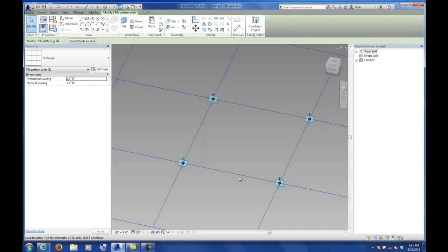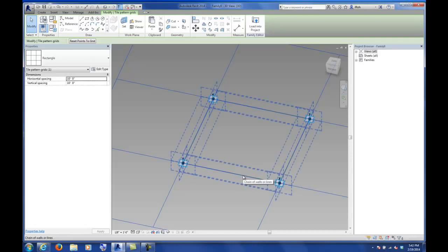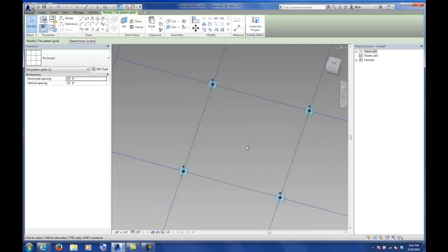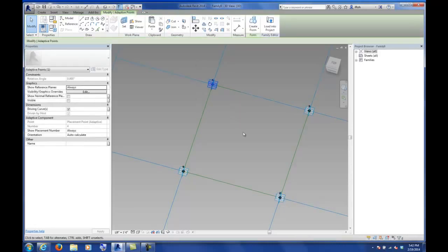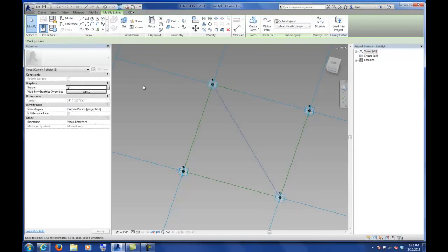And so I'm just going to do a quick little die-grid, which is basically a rectangle or some kind of square with a diagonal through it, and then we'll put some solid geometry to it. So to do that, I'm going to select point number 4 and point number 2, and I'm going to use the spline through points to make a straight line. And in this environment, everything we do, we want to make it into a reference line.